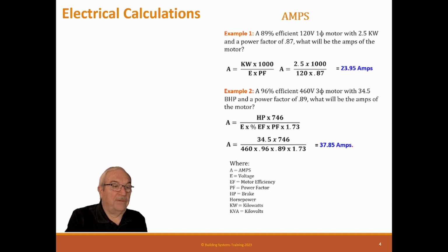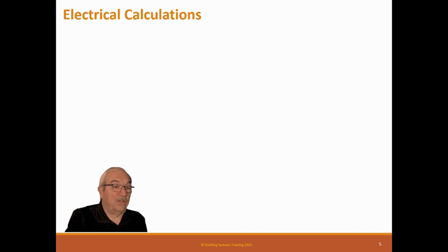Fractional motors can be 0.65, 0.66, 60% efficiency, or much less, because they're just not capable of getting high efficiencies in the motors we buy anyway. There might be really efficient motors out there that I don't know about, but the standard motor we buy is not that efficient, and even a premium efficient small horsepower motor is not very efficient.